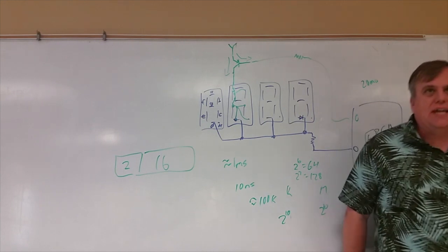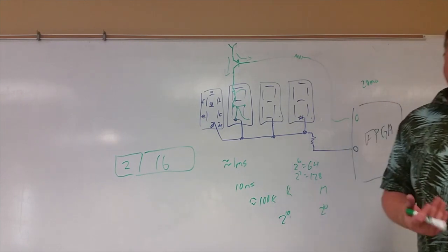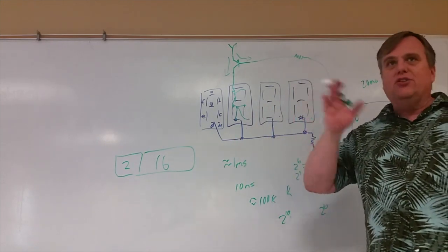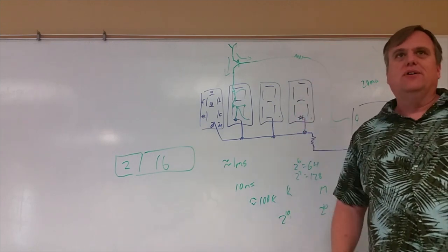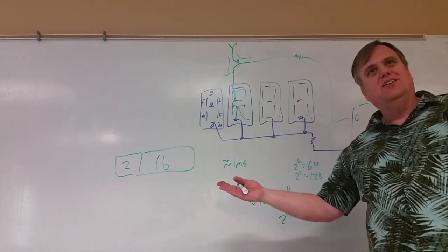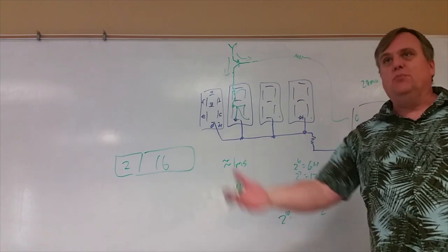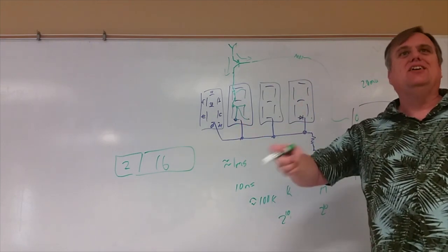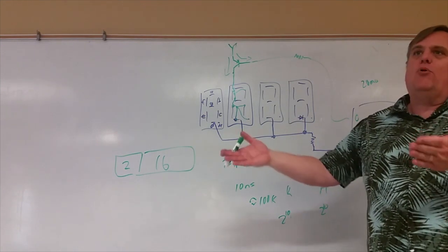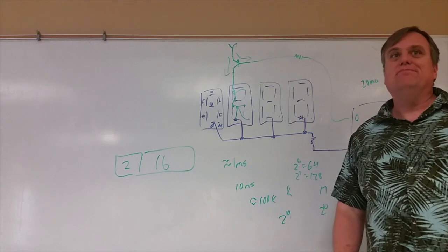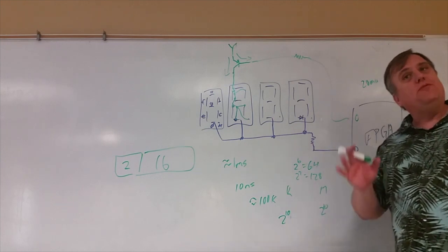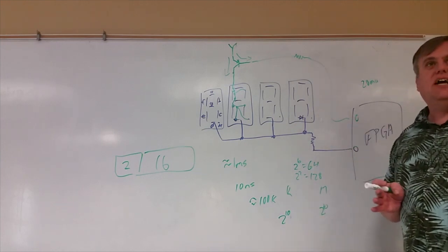Yes, you can actually take the code from the book, the 7-segment display and the stopwatch, and all you need is a clear state and then this random state, to tell you when to start going. So when you hit the start button, it doesn't immediately start counting, right? It will pick a random number and count to that, turn on a light, and then start the stopwatch. So you have a stopwatch plus one extra state. That make sense?